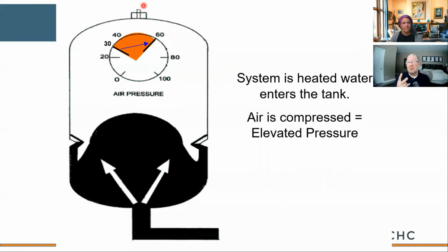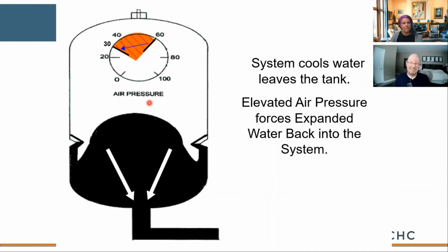I'm going to tell you it takes about 2 weeks, but eventually you'll let all the air out of the tank. The tank becomes what we call waterlogged, meaning it's full of water but has no air to push it back into the system. And now we start popping relief valves on our boiler. And the call we get is, hey, your boiler sucks. It's making a big mess in our mechanical room. Stop touching our expansion tank and the problems go away, all right? So guys, that's the importance of an expansion tank. It allows our system to expand and contract.